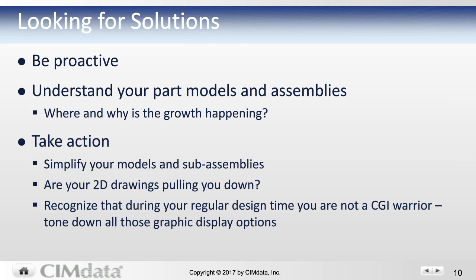Second, that CAD wonder function, that 2D drawings automatically update when you change the 3D model, can actually be a double-edged sword. It takes time to do those updates. Depending on the settings you have for the interaction between your 3D models and your 2D drawings, you can actually be dragged down in performance as you interact with the 3D model.